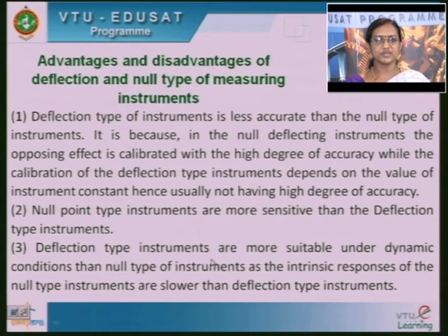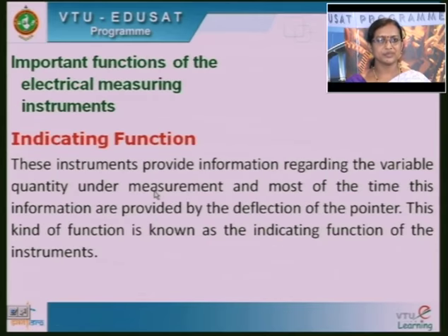Deflection type instruments are more suitable under dynamic conditions than null type instruments, as the intrinsic responses of null type instruments are slower than those of deflection type instruments. So, we are using mainly the deflection type of instruments in our laboratory.